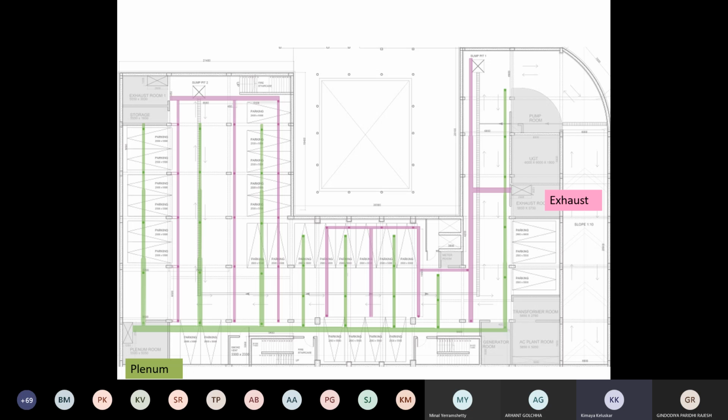To make sure that the required amount reaches the last grid, you need to maintain pressure throughout the length of your duct. That can only be done when you start reducing the duct, and that's why the duct has a telescopic form as it moves away from the plenum. Also, I used the word PSI, that is pounds per square inch.